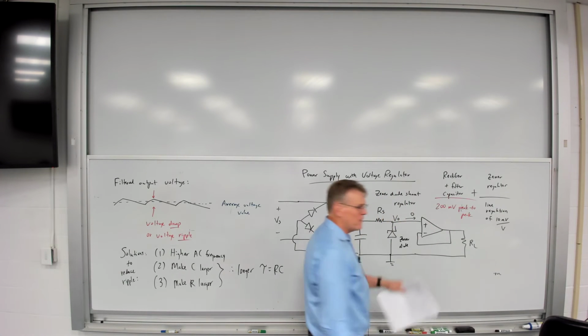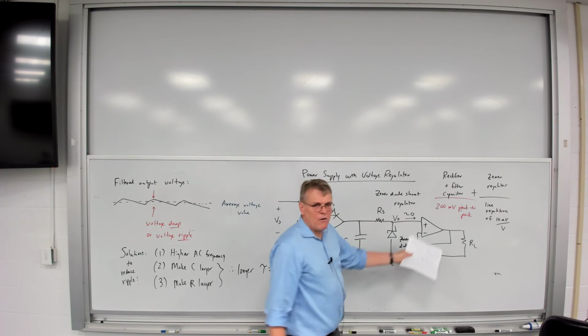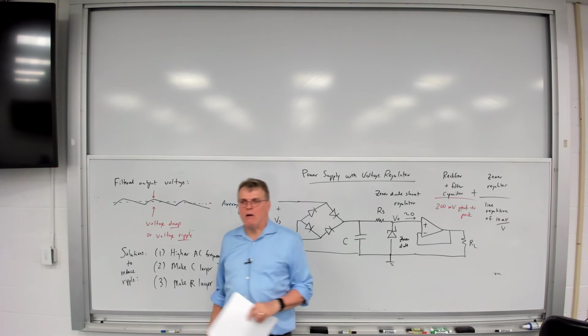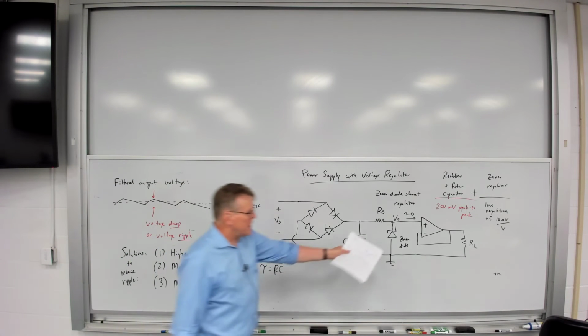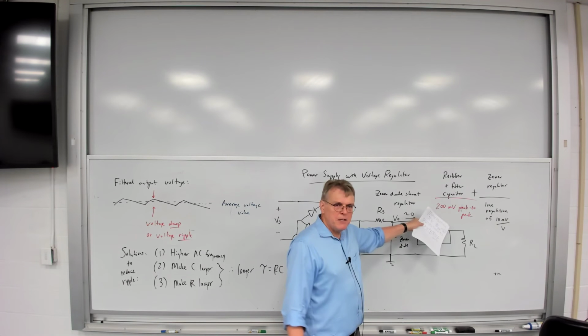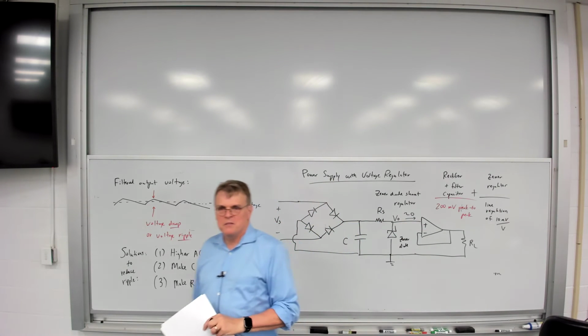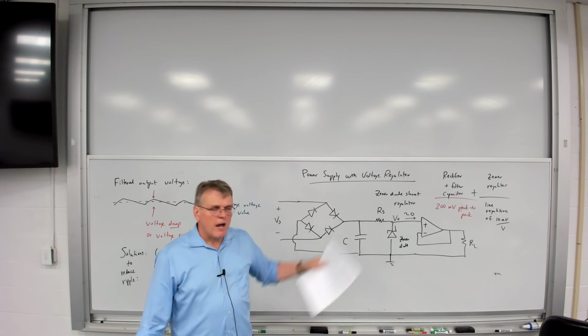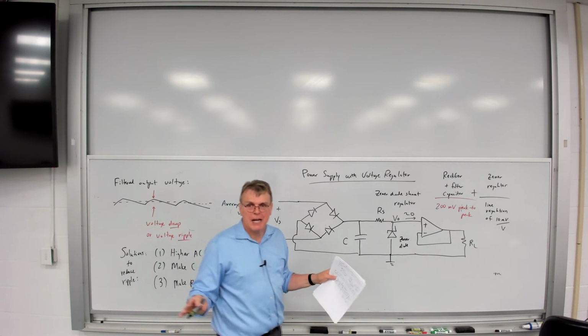Now the input current to the op amp is essentially 0. And now I'm separating RL so that I am eliminating loading effects. So now the op amp itself, a unity gain buffer, is going to supply the current to the load. So just as we saw before, that op amp is going to severely reduce any type of loading effects.